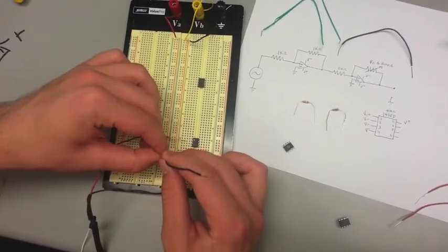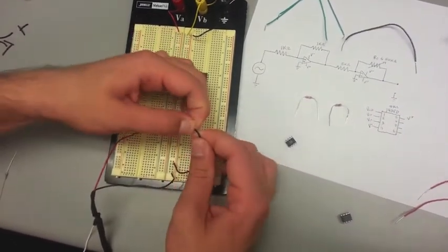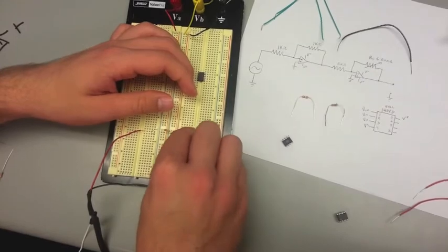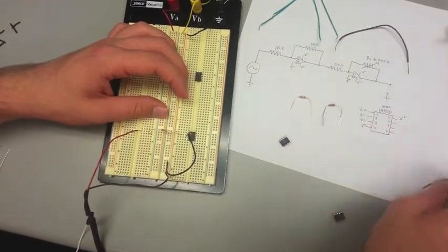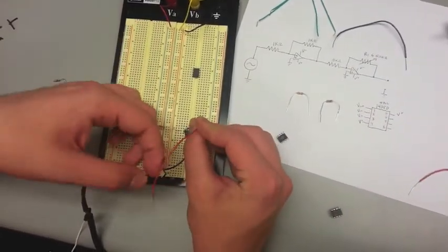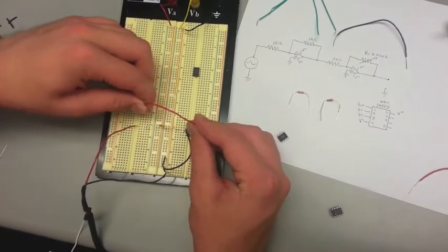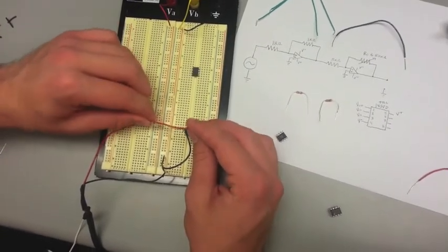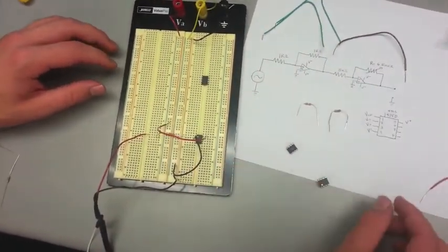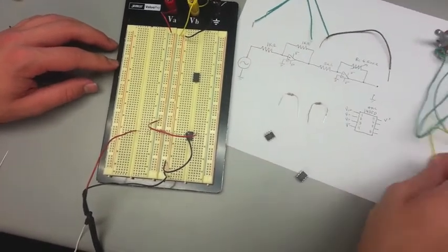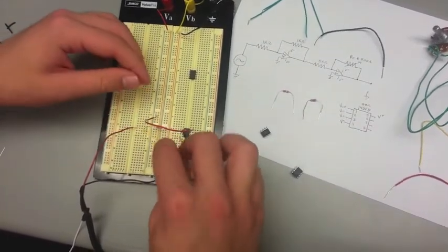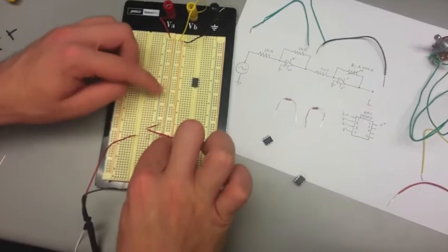and we go back to the black column that we used earlier for the input ground. And then we will use red to denote positive, and so positive goes into pin number 5, which goes to the positive rail, which is the one on the left for our operational purposes. And then we have to do the ground. Actually, we already did the ground. Rather, we need to do the negative input, which is going to be yellow. The negative goes to the 4th pin on the left, or pin number 4, and that goes to the middle, or the negative rail that runs all the way down the board.